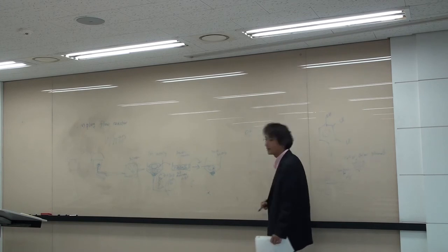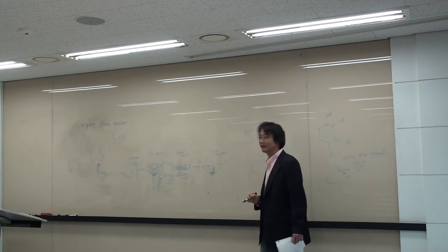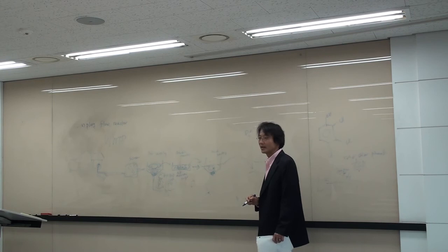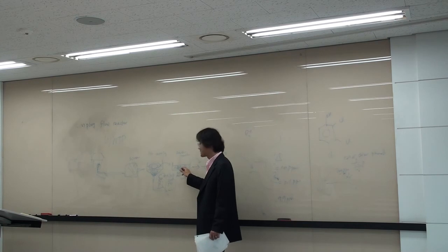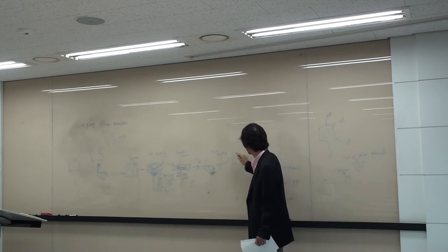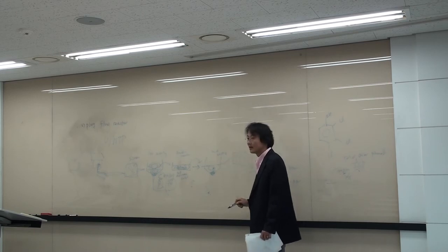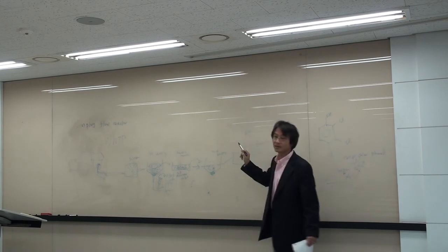Here is the catchment area, and then you can discharge this directly. But nobody wants to do this, right? Because some of you may wonder, what if these microorganisms contaminate our ecosystem? So what people usually do is put one more process here which kills microorganisms. We call it disinfection, using chlorine and other oxidants.